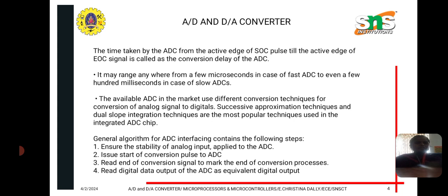We have both fast as well as slow ADCs. The ADCs available in the market use different conversion techniques for converting the analog signal to the digital signal. The successive approximation technique and the dual slope integration technique are the most popular techniques used in integrated ADC chips.